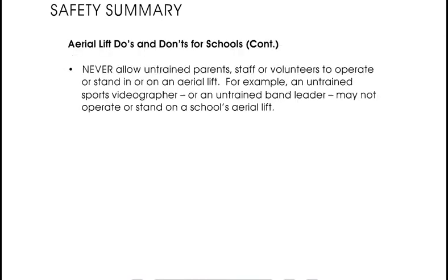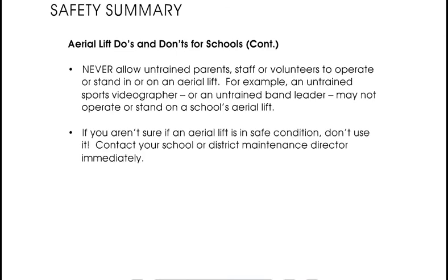Never allow untrained parents, staff, or volunteers to operate or stand in or on an aerial lift. For example, an untrained sports videographer or an untrained band leader may not operate or stand on a school's aerial lift. If you aren't sure if an aerial lift is in safe condition, don't use it. Contact your school or district maintenance director immediately.